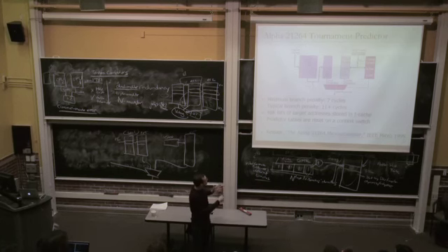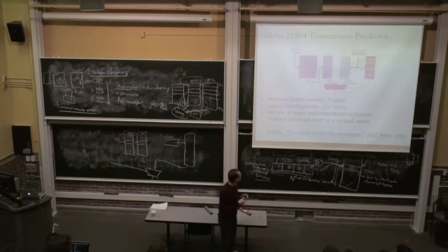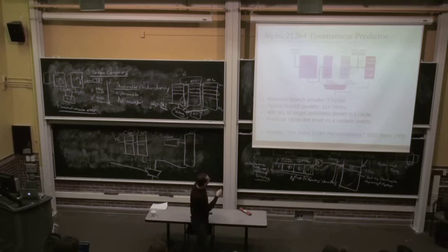And of course, sometimes you may want to size up, you may want to increase your clock cycle a little bit because you gain a lot more in cycles per instruction, right? Again, that's the trade-off they made. But in that machine, minimum branch penalty was 7 cycles, and typically they saw 11 cycles because it was an out-of-order execution machine. And this was their branch predictor.